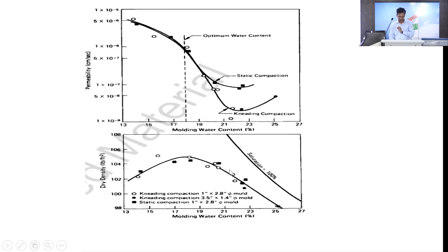So you also have the laboratory testing; somebody has given that the permeability of this material is 1.3 times 10 to the minus 6, and that is not sufficient. At what moisture content is he talking about? Wet of optimum, dry of optimum? At whatever moisture content you compact, accordingly you will get that result. This is one aspect which needs to be taken into account at the site. Next,